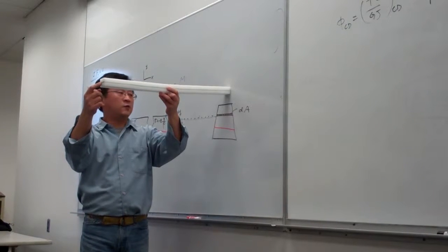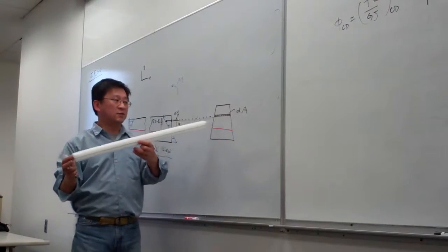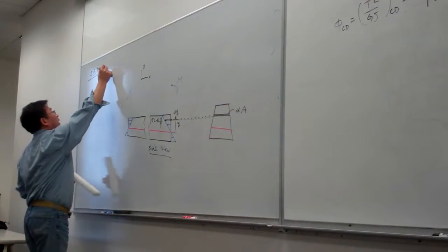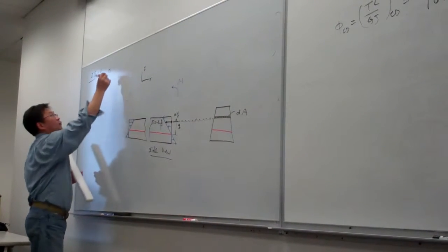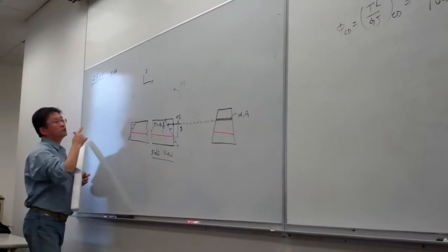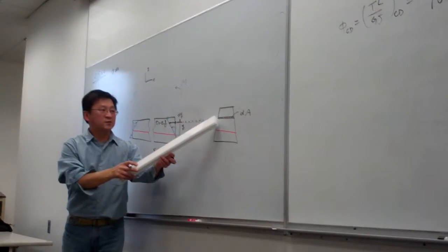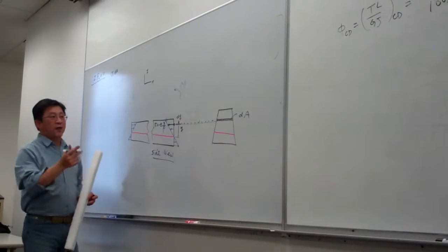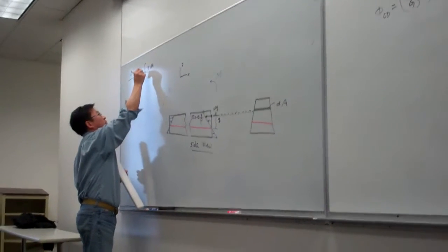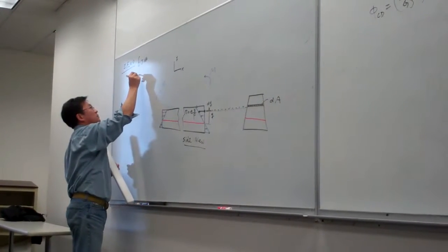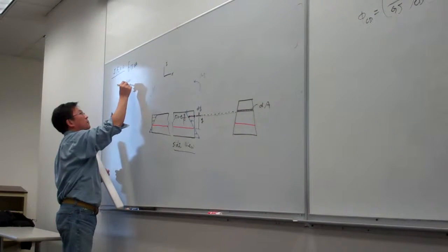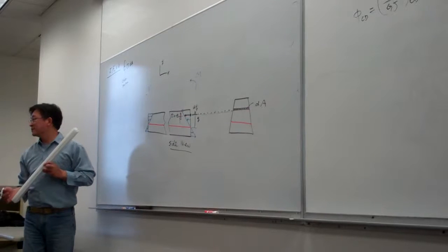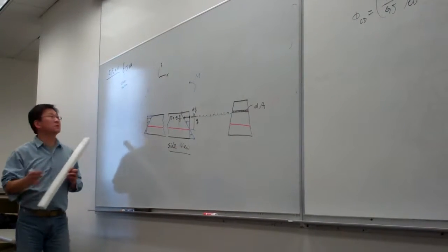And the equilibrium equation in this direction means the summation of the stress over the area. So we take the stress and multiply it with dA. This represents the small force due to that reaction on this strip. And I take the area integral on the cross section. So this represents the total reaction force in the axial direction.